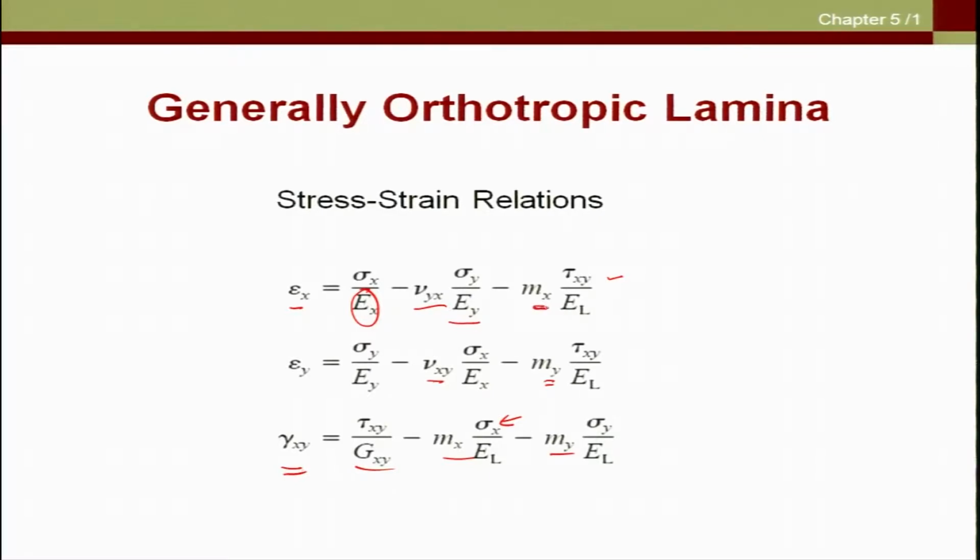And because MX and MY can be very large, shear stresses can create significant extensional strains, and extensional stresses can create significant shear strains in a generally orthotropic lamina.